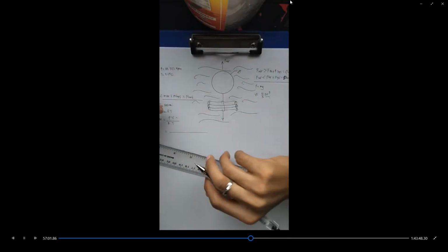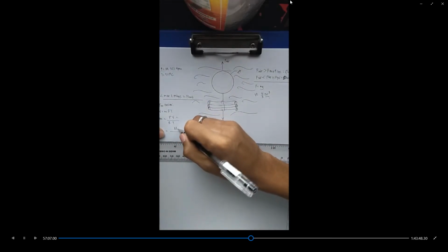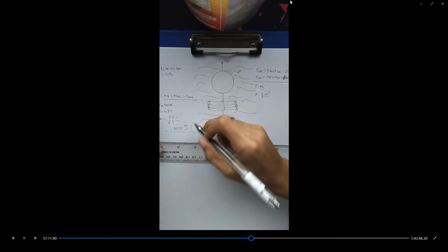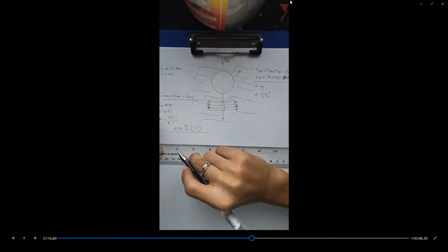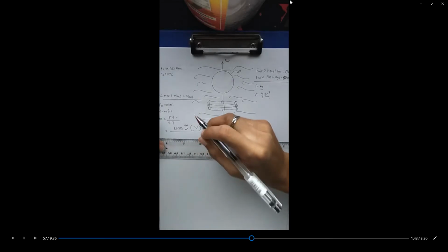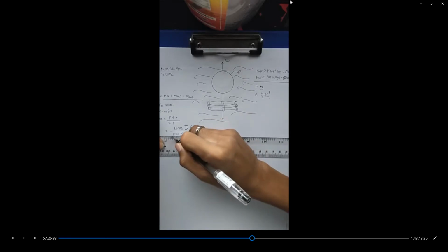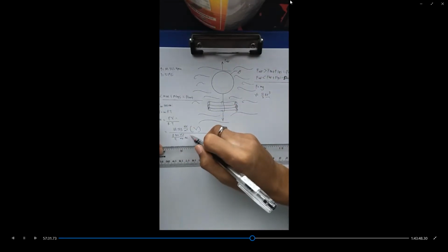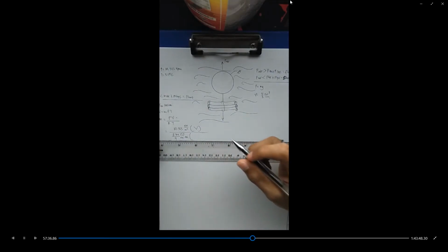Now, solving for the mass of our helium, we already have a pressure of 101.325 kilonewtons per meter squared, and our volume is unknown, so I'm just going to put it as V. Then the gas constant for helium in the metric system is 8.314 kilojoules per kilogram degree Kelvin divided by the molecular weight of helium, which is approximately 4, and the temperature of the surroundings is 21.1 degrees Celsius.